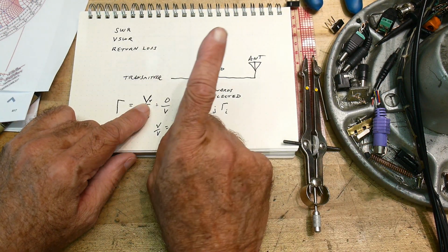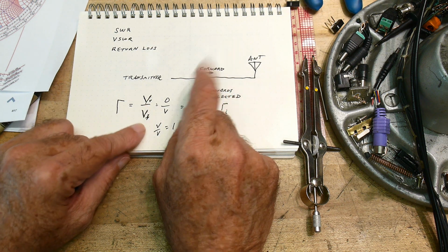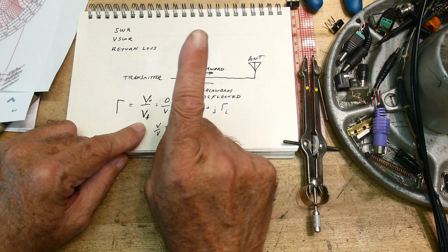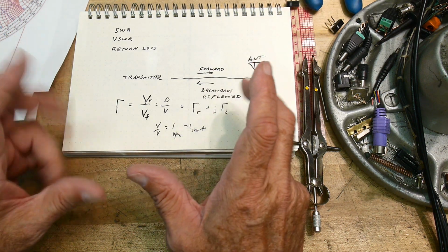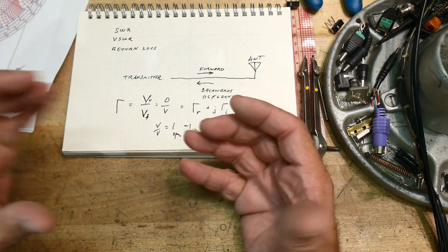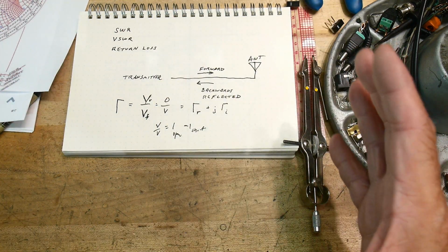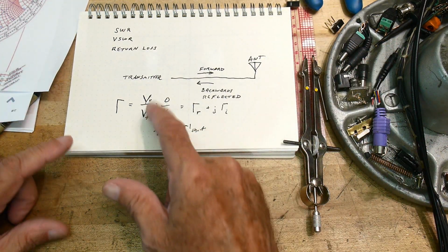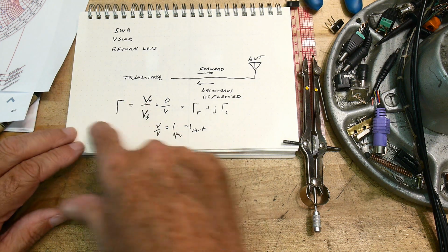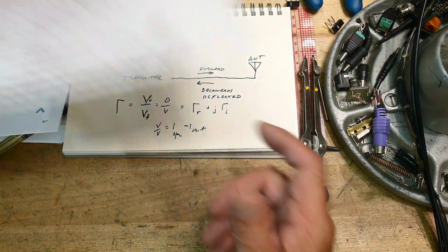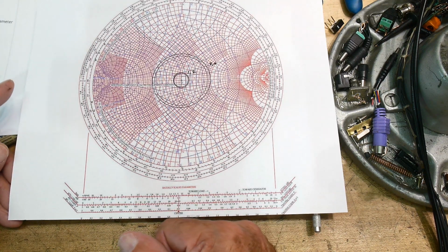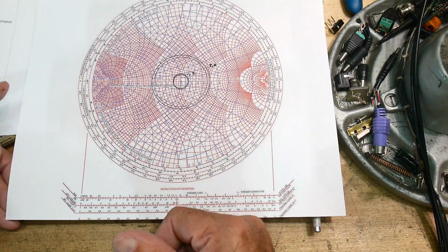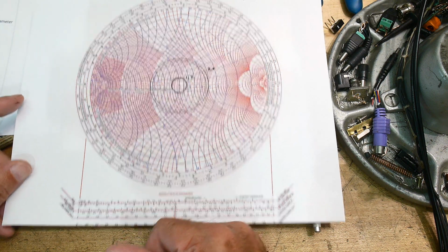Now, this is a vector voltage, though. It has both voltage and phase information in it. And this one has voltage and phase information. So you need what's called a vector voltmeter. So back in the old days, you could actually buy vector voltmeters. They were actually a big box, and you would measure the vector volts, and then you would do the math yourself, and then you could grab your piece of Smith chart, and then you could plot it on there yourself. But yeah, they were vector voltmeters, but the VNAs all do it for you now.